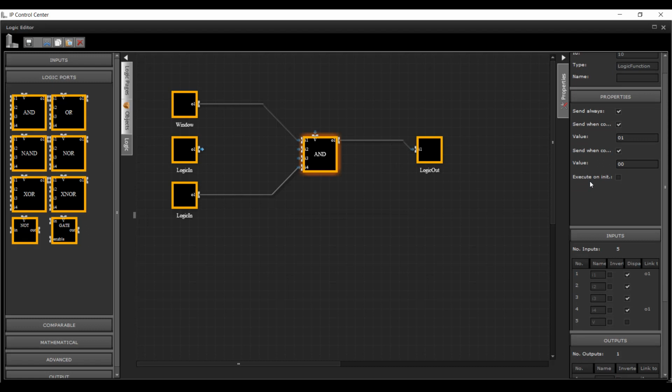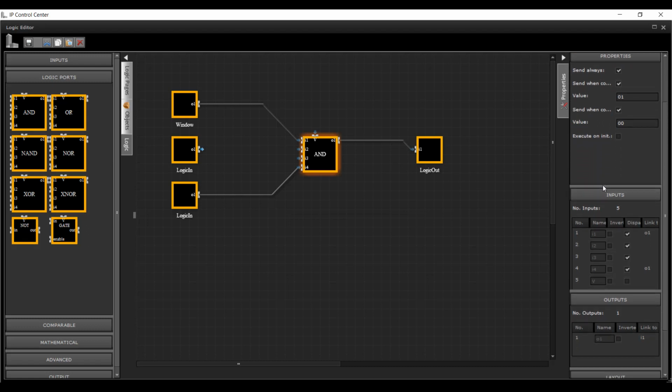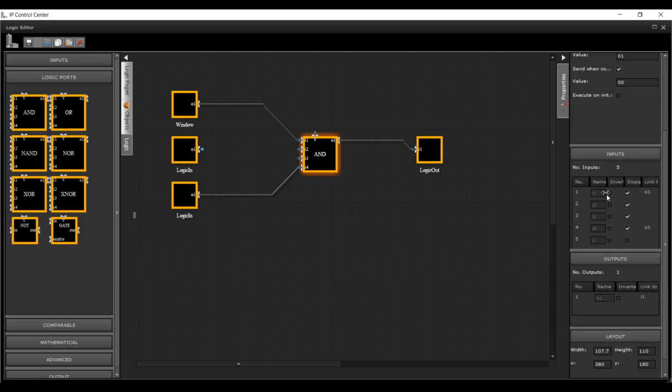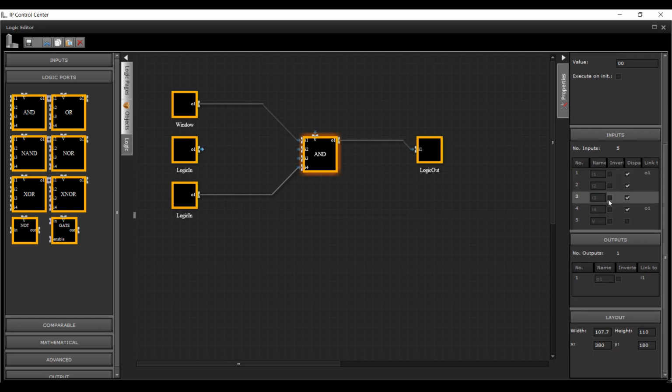Note: the following rules must be observed during inversion. Binary values are inverted binary: 0 to 1 and 1 to 0. Analogous values are negated. For example, 5 to -5 and -10 to 10. The assigned data point type is checked during the process.